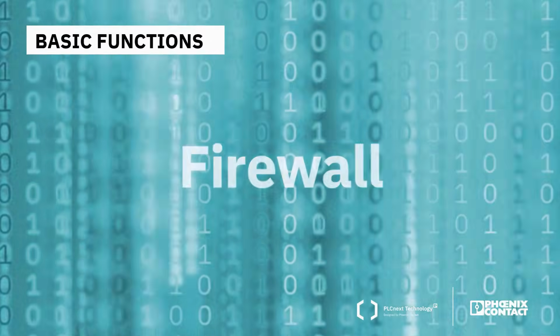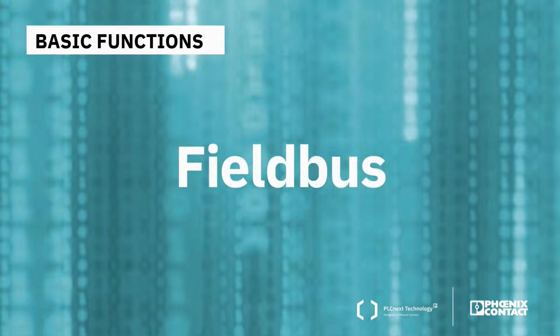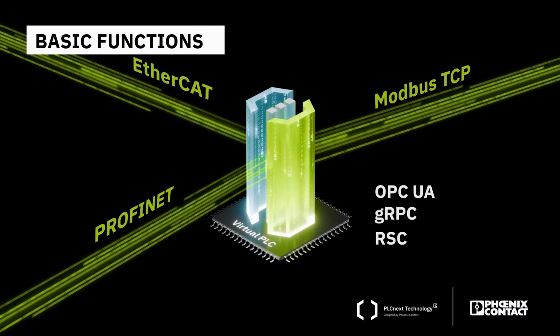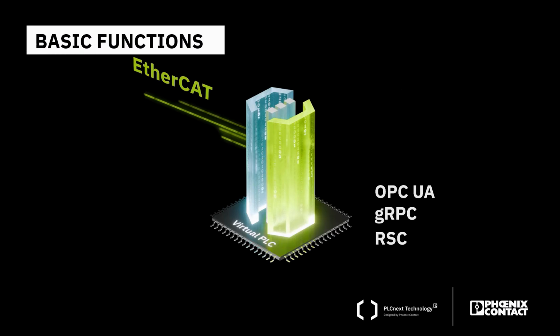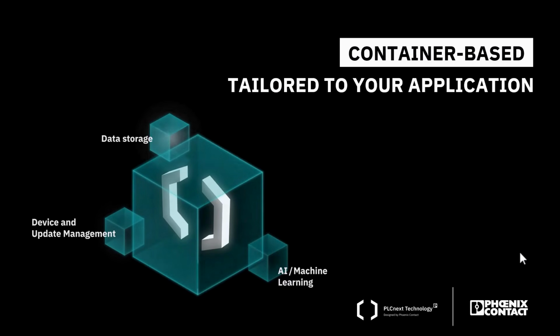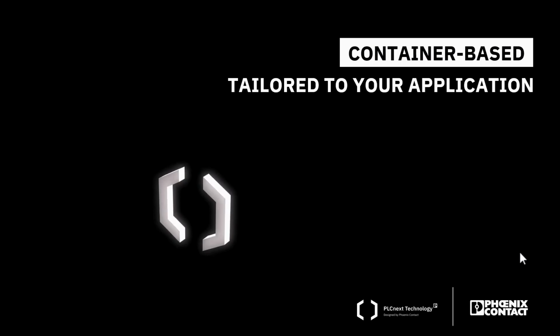For example, this can control a machine via I/Os and especially collect data from any PLC or sensor that speaks common Ethernet protocols like Profinet, OPC UA or Modbus, or is even connected via bus coupler to our device directly.